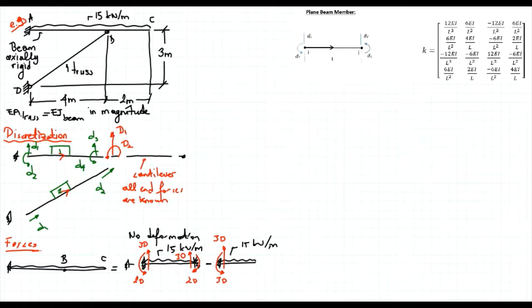Plus no deformation case, sorry, only deformation case. Now we say that the unbalanced forces create nodal deformations, and with the help of the nodal deformations, these unbalanced forces are balanced. The unbalanced forces for this structure, that's point B, are as follows.